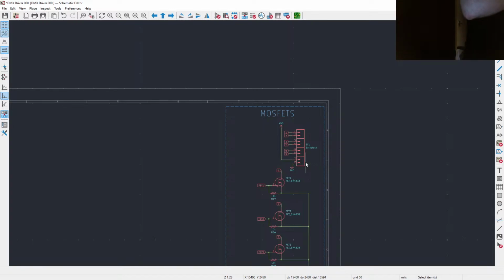I think the full CCT strip can push a good amount of power. And even those I haven't had much issues with in terms of getting hot, and they're easily pushing near the 3 to 4 amp range at full brightness, that is, which I'm rarely at full brightness. Just haven't had the need for it.